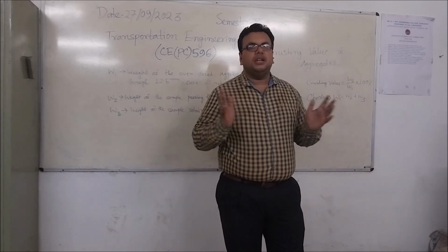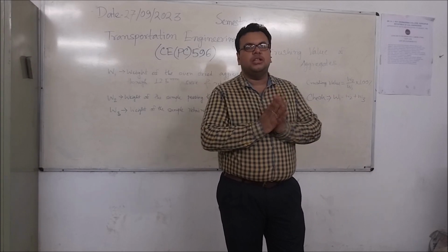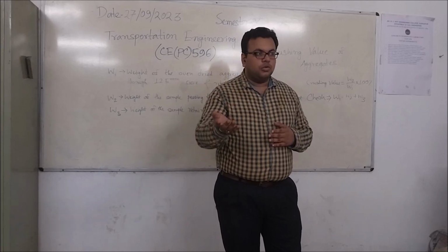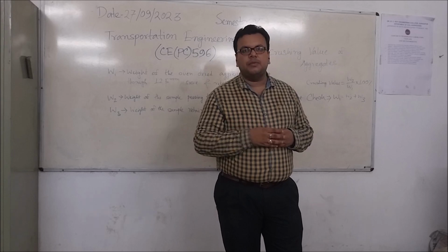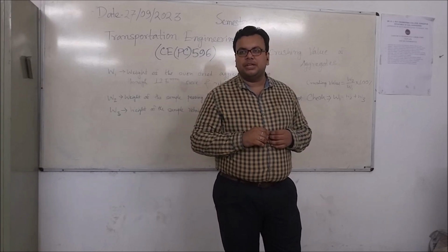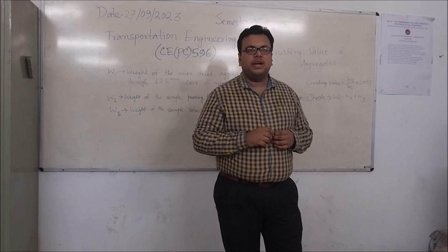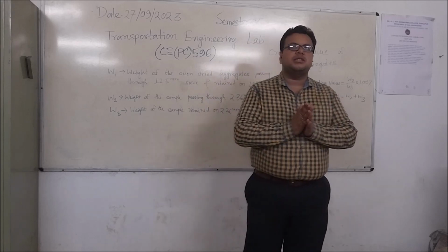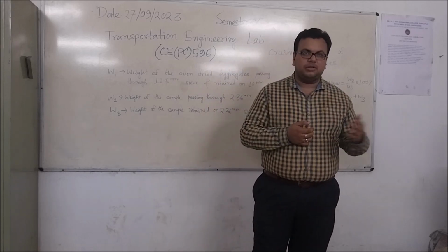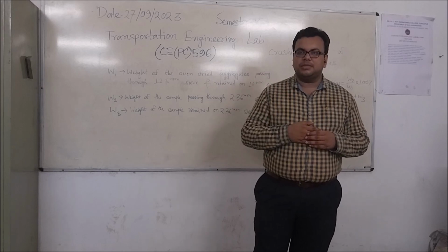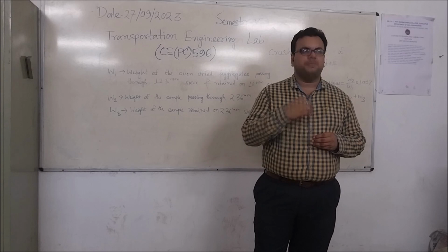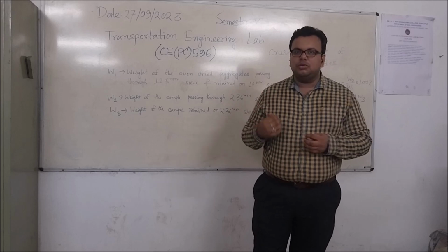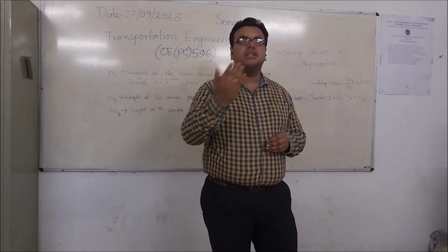Because crushing means it has been crushed under the huge amount of load applied to this particular sample. A similar phenomenon happens in the road itself, the highway or different types of roads. The huge amount of load due to the traffic comes onto the road surface, and that is why the aggregates will be crushed after some point of time. When the aggregates are crushed, we take that weight here in our laboratory with the help of the 2.36 mm sieve. The aggregate which passes through, in other words the crushed aggregate, we take as weight W2.